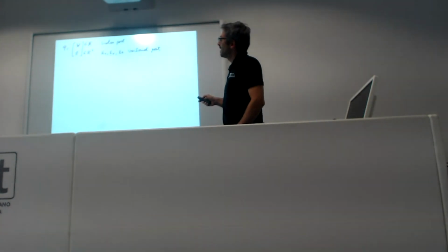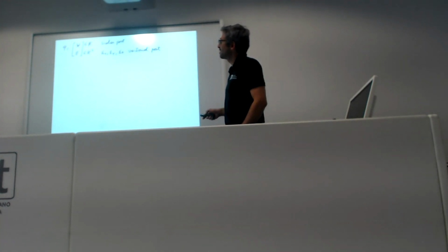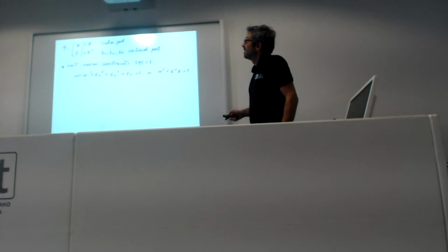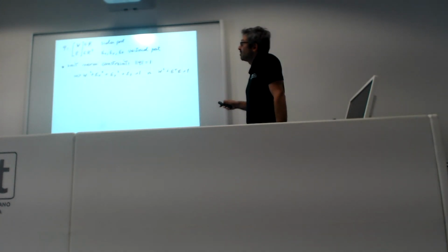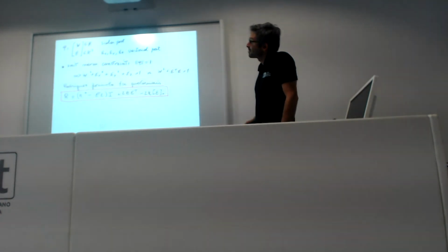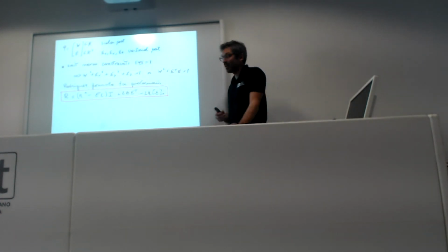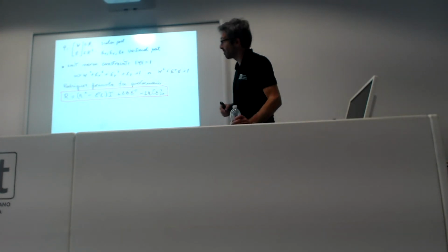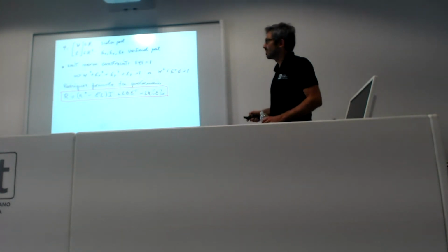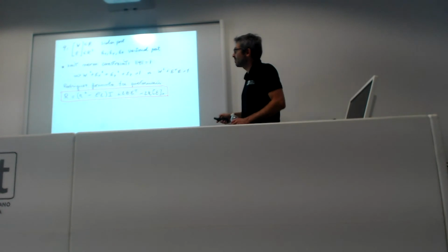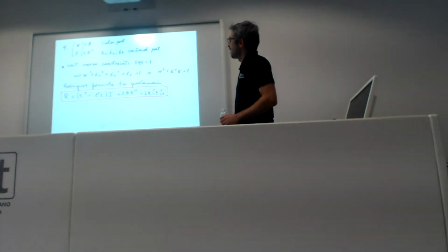The vectorial part is called epsilon. The scalar part is mainly called W. Then you have a unit norm constraint that completes the norm, which can be expressed this way. And with the Rodrigues formula, you can link quaternions to the rotation matrix if you need, using the scalar part and the vectorial part.